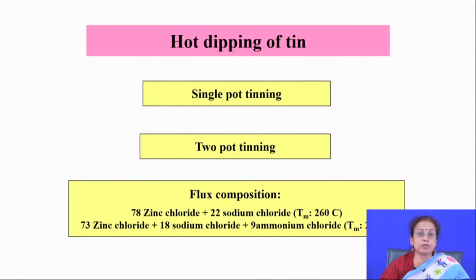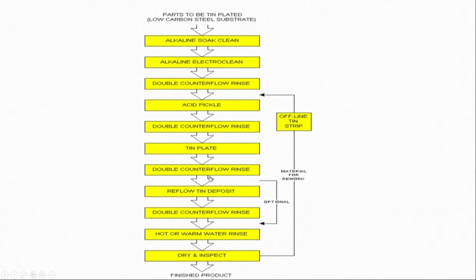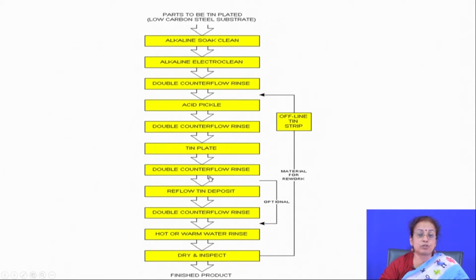Now, whenever you talk about the hot dipping process, there are also several other parallel techniques which you should know. Similarly for tin coating, a parallel technique is, for example, electrodeposition of tin. Electrodeposition is often applied and preferred to the hot dipping process, because after hot dipping you have to go for a machining operation, as the hot dip layer is basically a melt and cast layer.